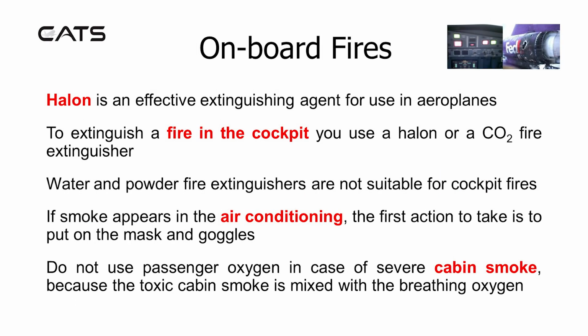Onboard fires. Halon is an effective extinguishing agent for use in aeroplanes. To extinguish a fire in the cockpit, you use a halon or a carbon dioxide fire extinguisher. Water and powder fire extinguishers are not suitable for cockpit fires. If smoke appears in the air conditioning, the first action to take is to put on a mask and goggles. Do not use passenger oxygen in case of severe cabin smoke, because the toxic cabin smoke is mixed with breathing oxygen.